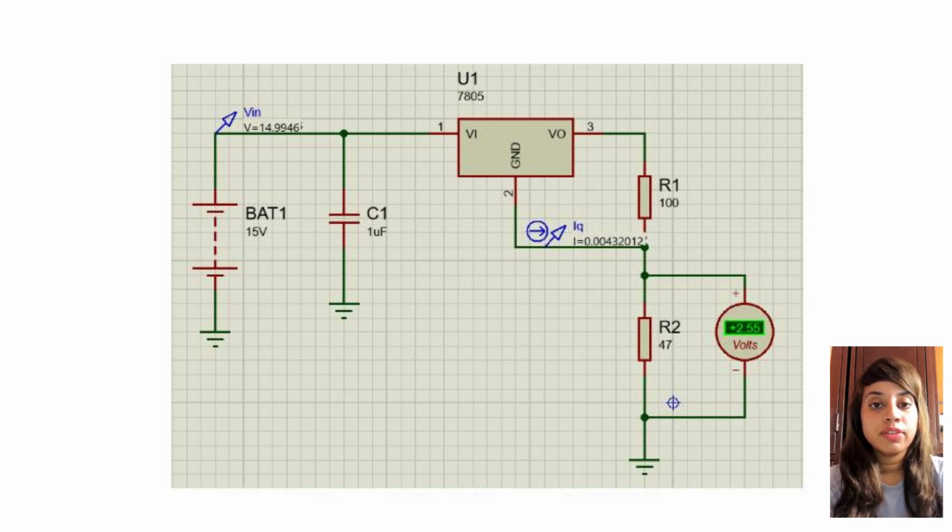Greetings to Dr. Nurmisa. Here I would like to present my part. Question D says: construct the adjustable output voltage regulator shown in Figure 6.4b. Measure the DC output voltage for values of resistor R2 that vary from 47 ohm to 220 ohm. Compare the expected output voltage from the pre-lab and the simulated output voltage value.